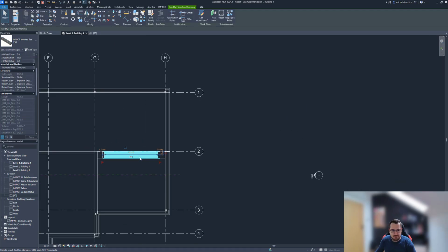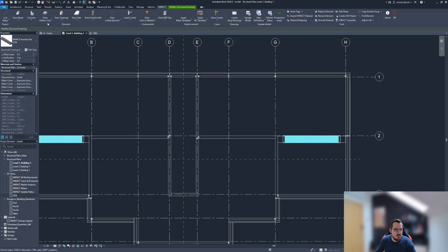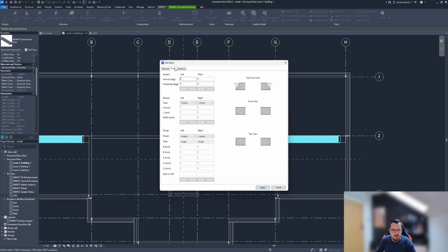So you can see, let's do that. So we can edit the beams that we have selected, and for example assign an opening, single symmetrical, let's go 80 for the diameter, and I think 70 or 65 should be good.